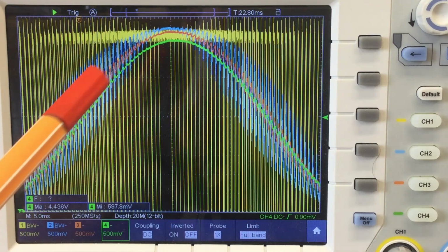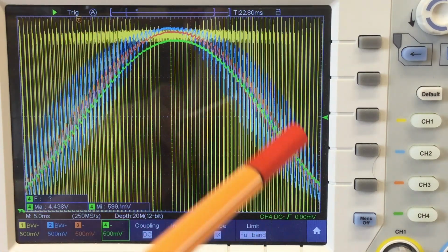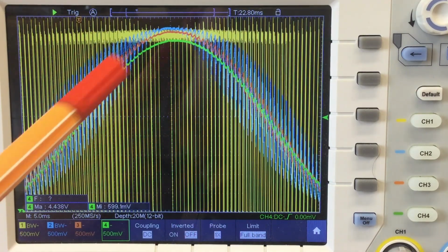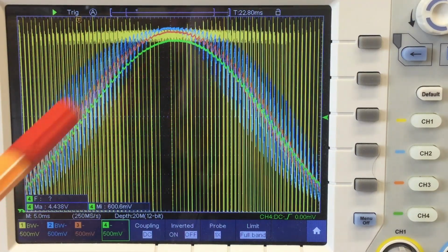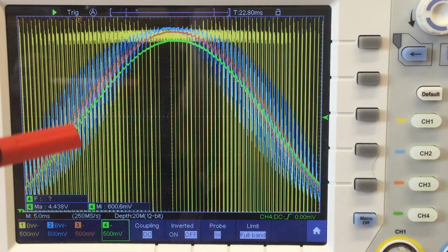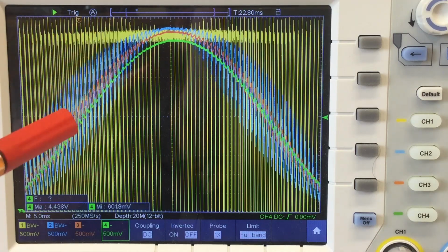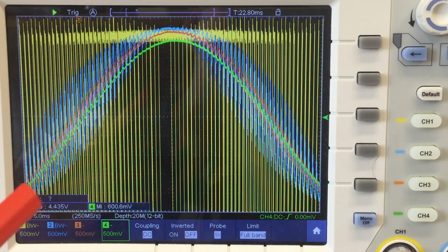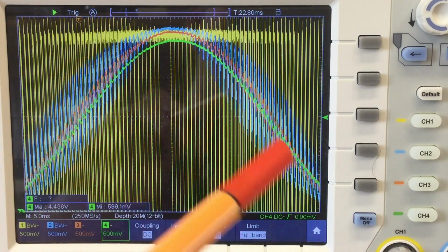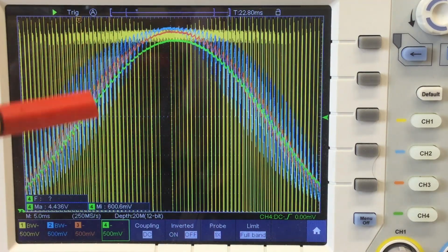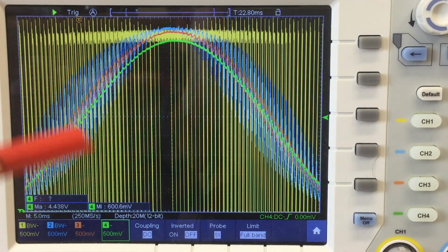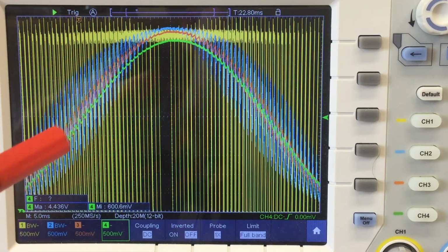Yeah. Second RC element output, much better. Maybe some people might be okay with that, but yeah, still some PWM frequency in it. And then green, our final output. Of course, it still contains some ripple. We designed it that way.